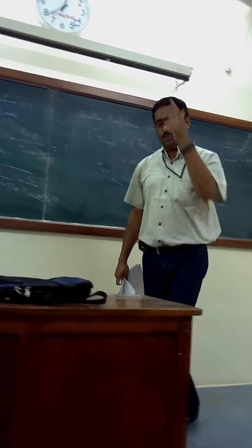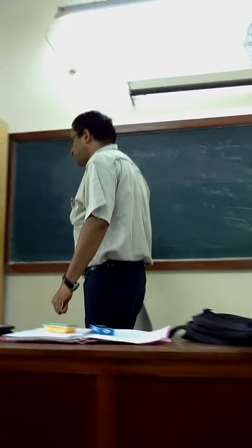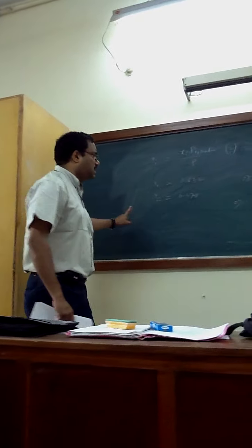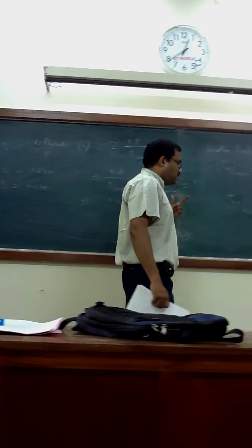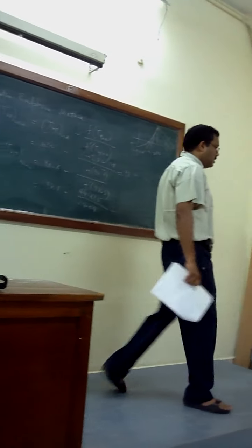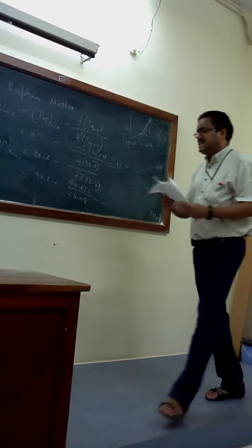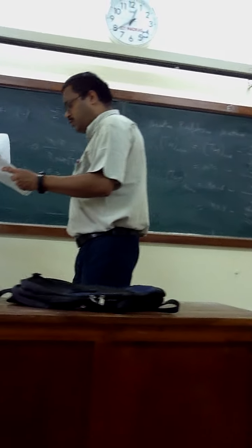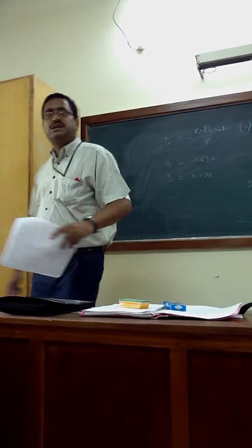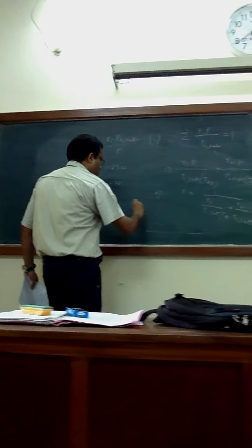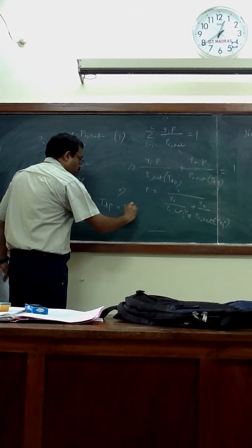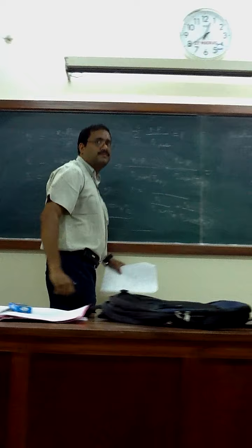You know that. In the first part it will dip directly to near the solution. So give an initial guess of 30 to 40 degrees and do the iteration using the numerical Jacobian method to get the answer. The answer is 52.4 degrees centigrade. The dew point is 52.4 degrees centigrade.